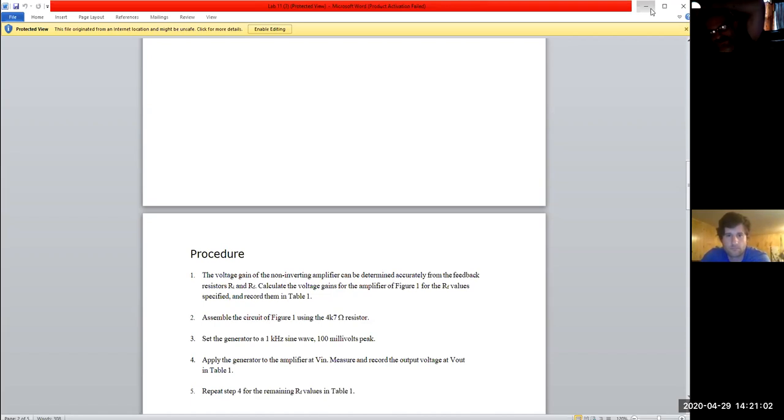And the cool thing is we use all three of those things at that point: op amps, transistors, and diodes, just for different purposes. With diodes, usually they're nice little blockers. A lot of times that's what we do with them, right? Keep unwanted signals out. So if you see a diode tied to ground or something like that, what's its purpose? It's blocking. Clippers, blockers, setting up little voltage thresholds. Diodes are pretty simple in that effect, but they're nice to use for that.